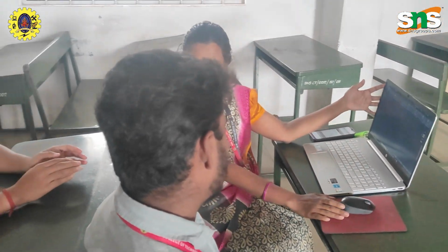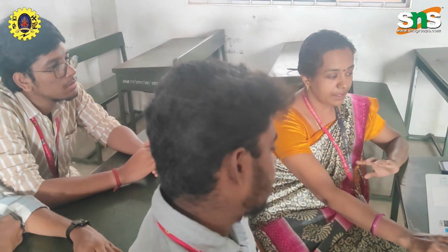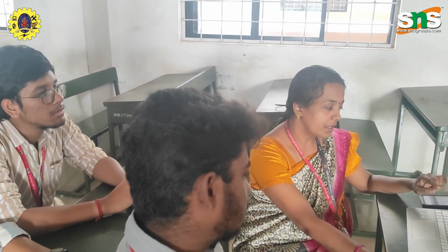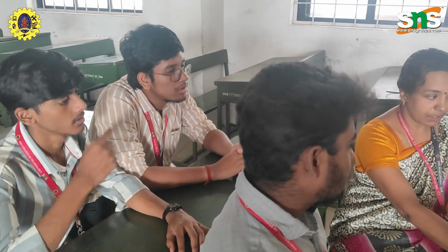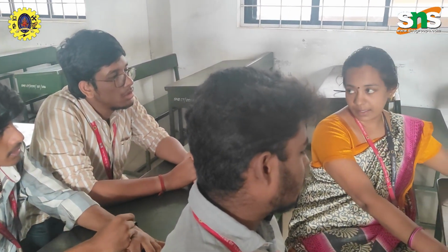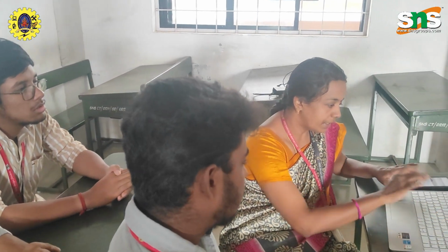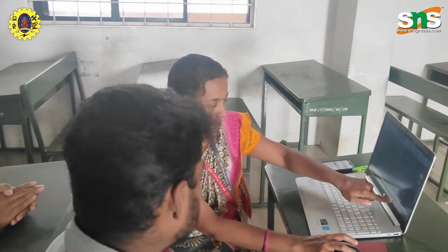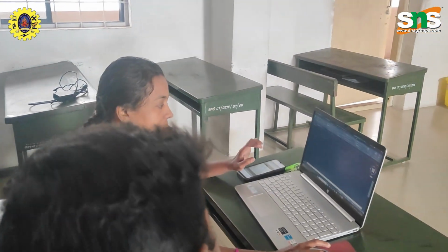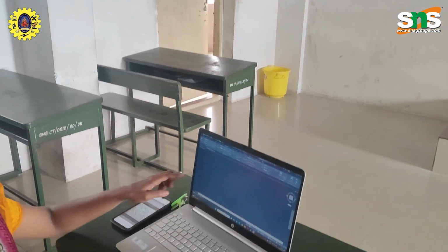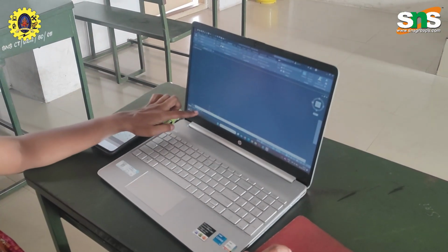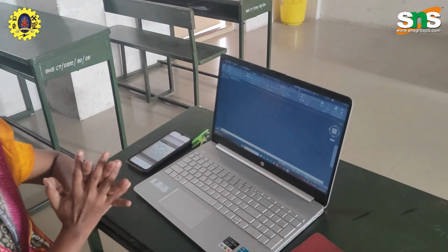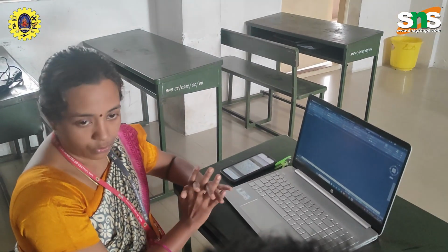So, anything you want to ask till now? How to access the command prompt? Yes, that's actually a good question. Here we don't have the command prompt. The command prompt is very important in AutoCAD for a designer. I have to press Control 9 and I get this prompt, where I can see whatever I type. Here in this cursor I can see whatever I type, and here also. So the command prompt is very important in AutoCAD software.